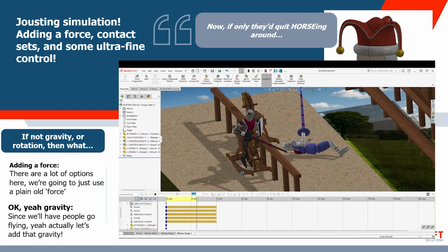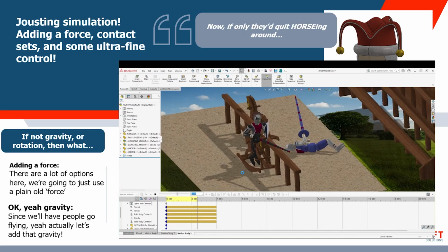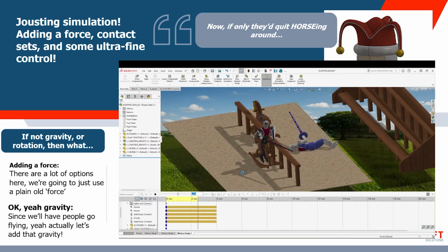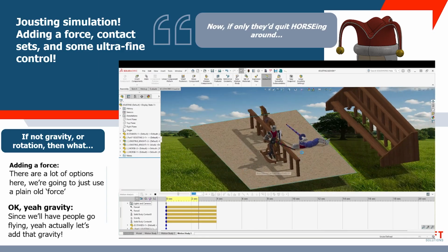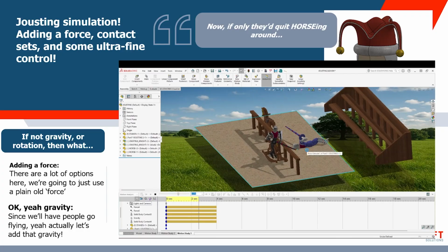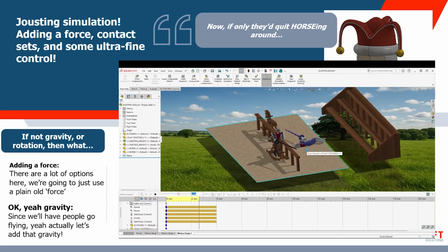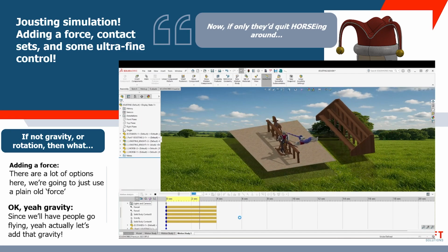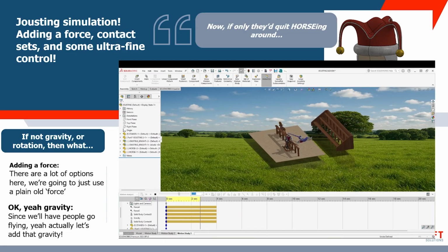Now this is going to take a little while to finish rendering, and this is maybe one of the things that I can say: don't have a situation, if you can avoid it, where you've got a solid mass, even if you have the contact set, that can move through a thin body like this, because it ends up no clipping into the back rooms. That one's for your youngins. It ends up kind of moving through and trying to solve to two different sides of the body. If I had made that sand thicker, this probably wouldn't be getting so hung up right here.